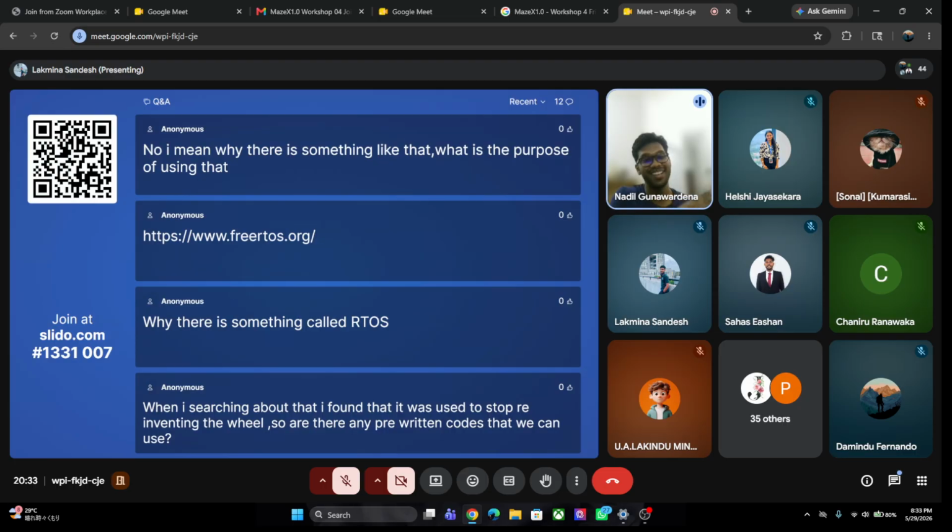But microcontrollers that do not have a dedicated register like that, you need to use interrupts, right? Interrupts means every time you hit an encoder step, you need to register that value and store it. The encoder step needs to be incremented by +1, +1, +1. You need to keep that count. We use interrupts because we need to interrupt the code that we are running to register the step. Otherwise, we would miss that step.